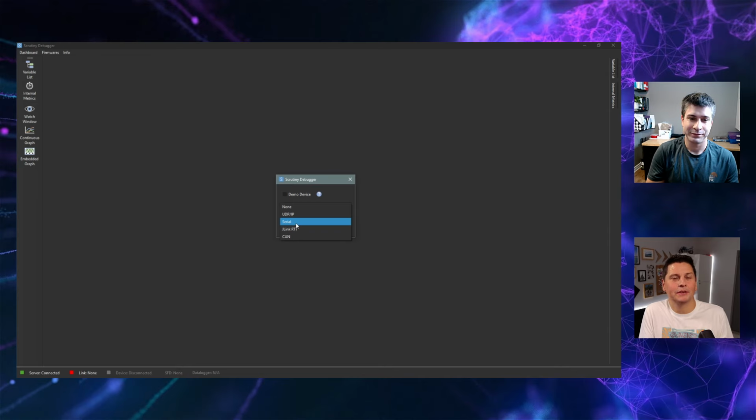You don't want to preempt the actual execution of a task that is higher priority. Otherwise, you're defeating the purpose of debugging because you're intrusive into how things should be working. Exactly. You want it to be lower priority, still emitting information, logs, and data, but not preempt the higher priority task. So you're totally respecting the hard real time structure of the device, of the system. Well, it's given to the control of the integrator.